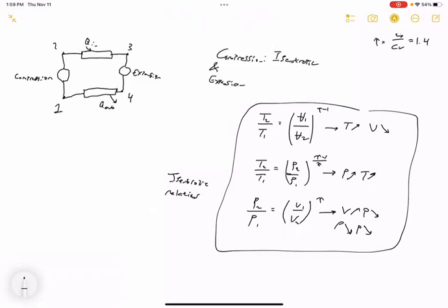Okay, so we've now covered processes like compression and expansion in the Otto cycle, but what about the heat addition and heat rejection processes? Are these isentropic? Well, you'll find out in class what an isentropic process really means, and one of the restrictions is that an isentropic process cannot have any heat exchange. So immediately we can say that heat addition and heat rejection are definitely not isentropic. But let's think about what's actually happening in a car engine and see if that sheds any light. Actually, I'll draw it the other way. I think it's a little clearer.